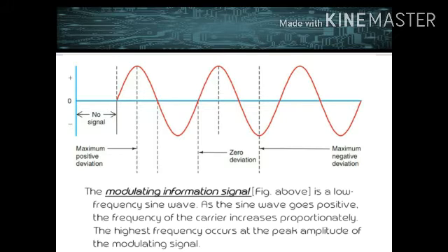Modulation is the process in which the carrier signal is varied according to the information bearing signal, also called the modulating signal. During modulation, some characteristic, which can be amplitude, frequency, or phase shift, is varied in accordance with the original information bearing signal that has to be transmitted. The modulating signal is nothing but the information signal. This modulating signal is primarily in two forms, analog signal and digital signal. Now, the difference between the carrier wave and the modulating information signal: the carrier wave is just a plain wave without information, while the modulating information signal is a signal wherein the information was put to be disseminated.